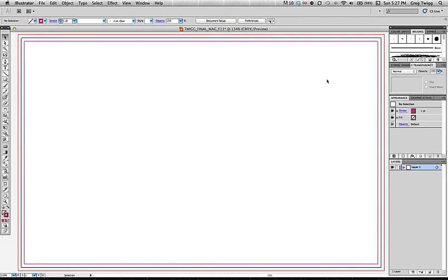This element that I set up, this gutter, I would like to put in its own layer. So with it selected, I'm going to go to my layer window, and I'm going to click on New Layer. So I end up having layer 2. And with that artwork selected, I can see that layer 1 has selected artwork.